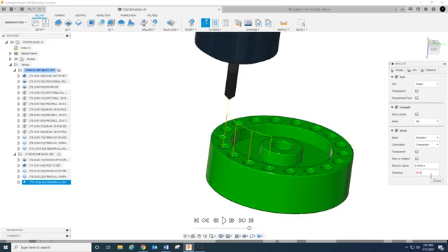If I was to go to like 2.5, see, we're starting to get into that noise. But then obviously if I was to go to like 1/10, now we're getting just crazy, because the computer can process these flat surfaces pretty easily, but these rounded surfaces, it struggles with those. So comparison is not really a valid tool when you need to get down in the tenths. But for 5 thousandths, it works just fine.